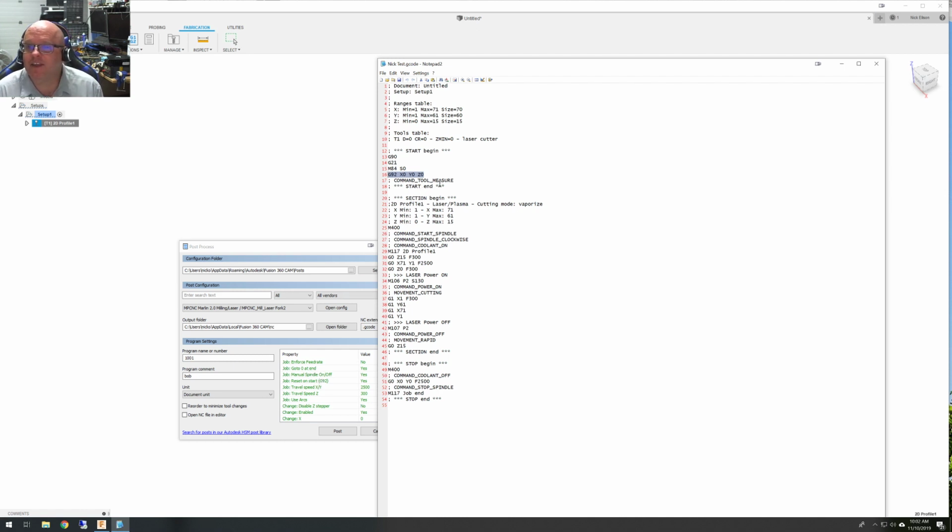And then it puts all these fun things in there. Look at all this extra goodies that he's telling me about. I'm using cutting mode vaporize, and it slaps some more stuff in there. This is one thing that bugs me about this particular post processor. The M117 command that it stuffs in there is the LCD screen. It's going to banner something to the LCD screen, and you got to press the LCD button to continue. It starts a pause. It says I'm about to work.